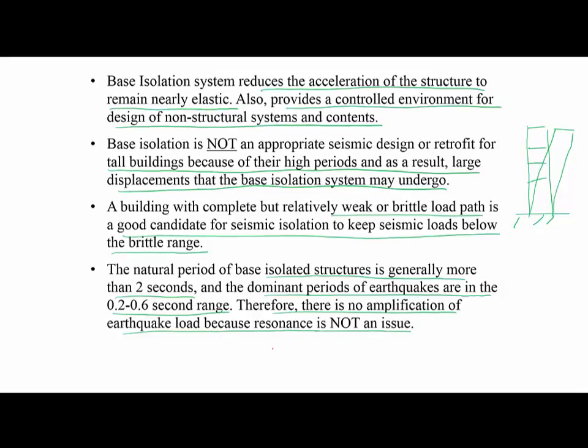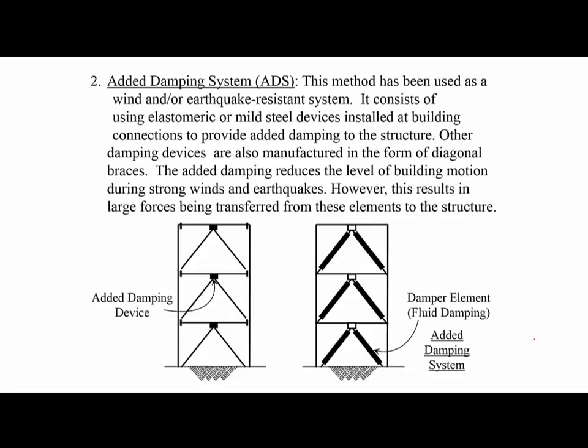Then again, we are looking at these 2 seconds for shorter buildings, low-rise buildings basically. Then that is possible. But if you have a tall building, obviously the base isolation system is not going to be a viable option.